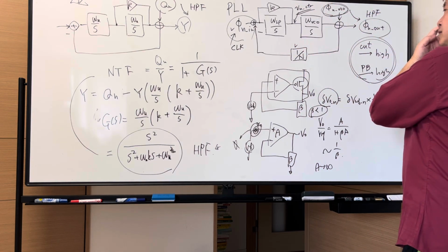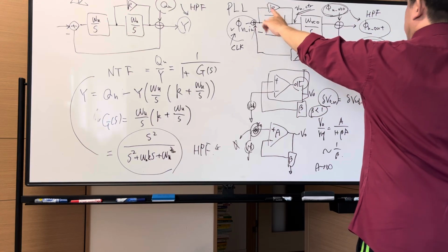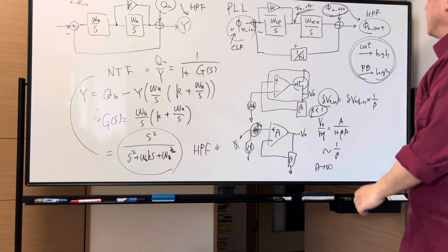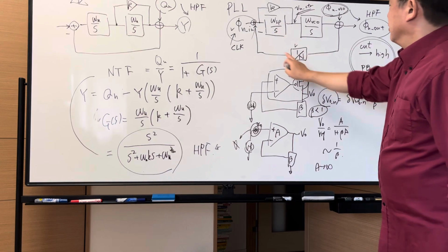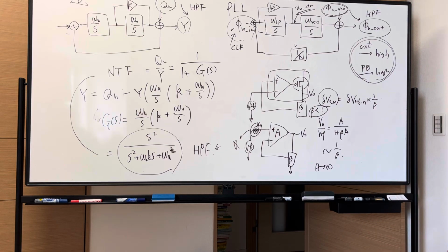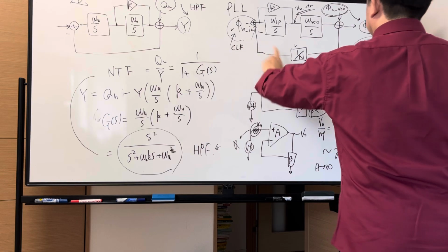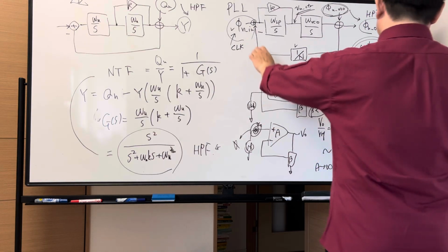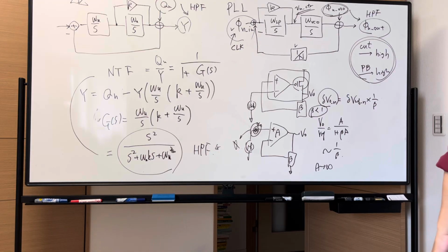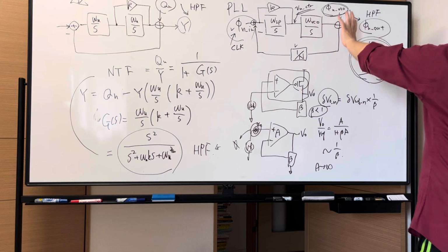And if we have enough decoupling capacitor and a very clean signal running through the logic of the feedback divider and phase frequency detector, and the input clock has the smallest possible jitter phase noise, then we can apply this logic to make the phase noise from the VCO negligible.